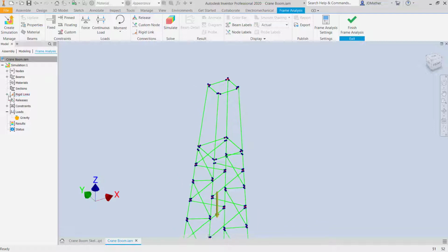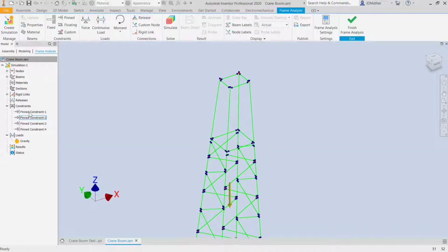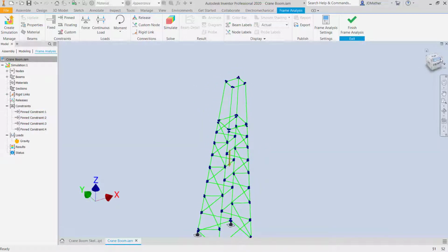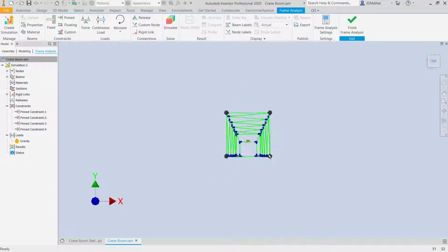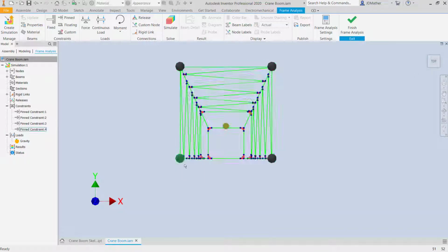And by the way, on these constraints that we just put in here, the pin constraints, we might want to give those a name, and I probably should have used a particular order, like these two and then these two, and let's just see how I put them in. So I did that one up at the top. I did that one, so I do have these in an order that would make logical sense, with these two being ordered together and these two ordered together.